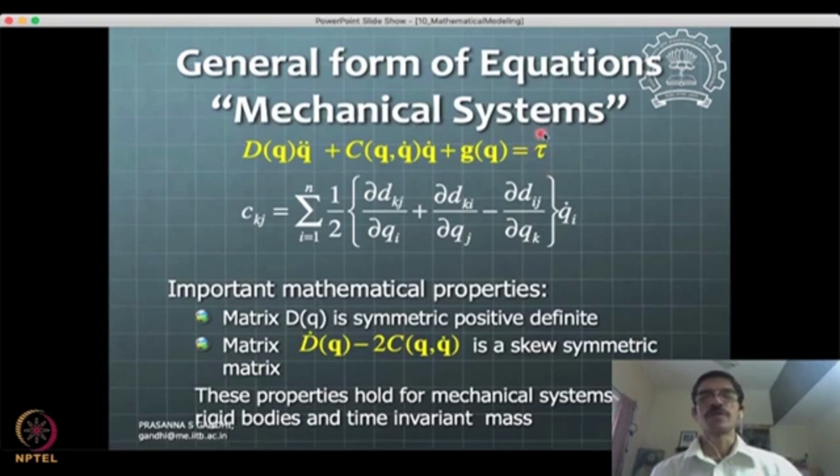Those terms are going to form the external forces in the system. As we saw, the damping will form an external torque in the system, and they will appear here, as external torques or external forces that you are applying. This tau is just a term, but it can be in force, torque or moment form, in the direction of the generalized coordinate.